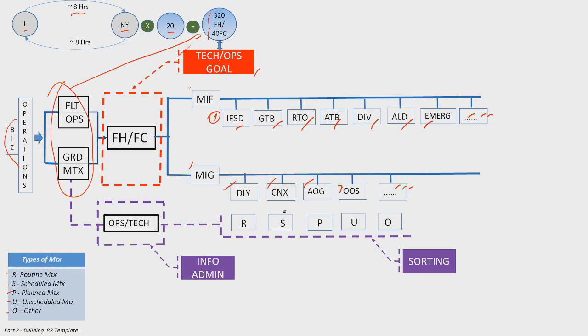What is the difference? Let me give you another explanation. I'm going to use again scenario 2 from part 1. So we said we had 5 scheduled removals, DC battery, and 15 unscheduled. Let me explain what it means. 5 scheduled removals means that we removed all these 5 items as per manufacturer MPD, MRB requirements, which was, if you remember, 3,000 flight hours. So all these 5 items we removed at 3,000 flight hours. What about unscheduled? Unfortunately, probably the first one was removed, well, let's assume, at 2,000 flight hours, the second one at 2,300,